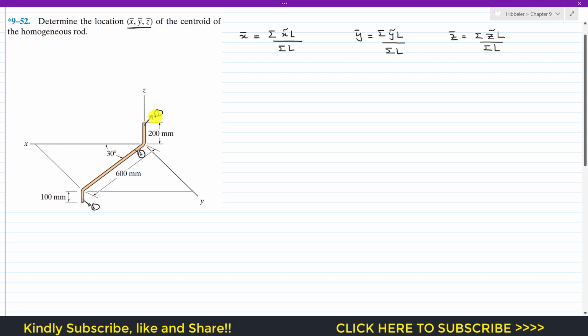So the centroid of this segment 1 will be at its mid length. So let's say this is C1. It is located at a distance of 100 mm from that origin. So the centroid of this segment 1 is lying on the z-axis. This means that x tilde 1 and y tilde 1 will be equal to 0, and the location of the centroid of this segment 1 along the z-axis is z tilde 1, and that is equal to 100 mm.